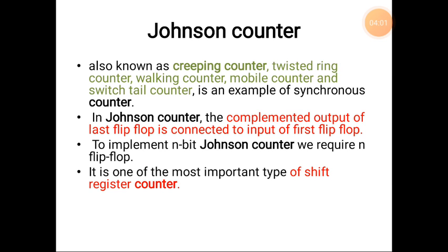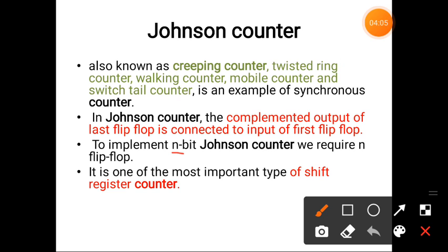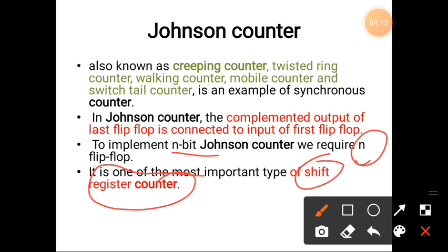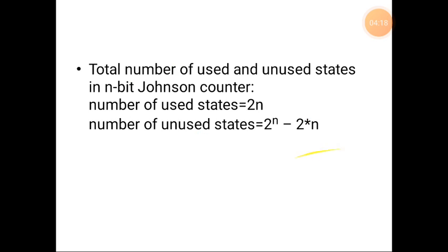To implement an n-bit Johnson counter, how many flip-flops do we require? We require n flip-flops, and it is a shift register counter. Next, the number of used and unused states in an n-bit Johnson counter.